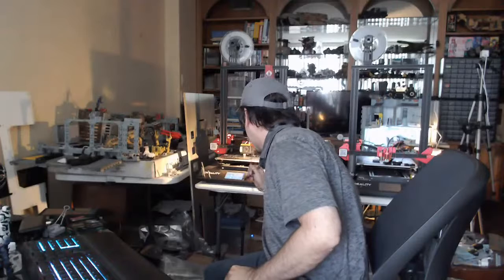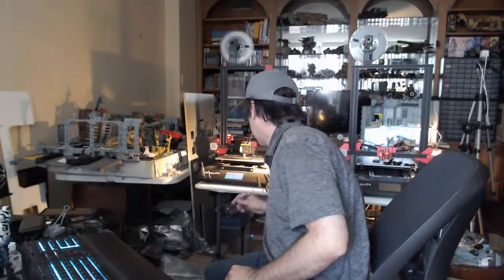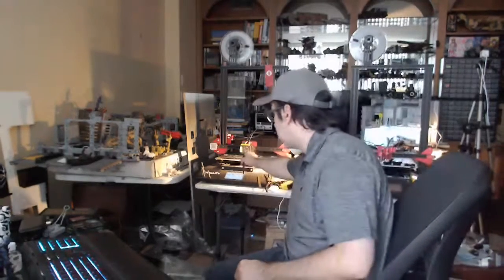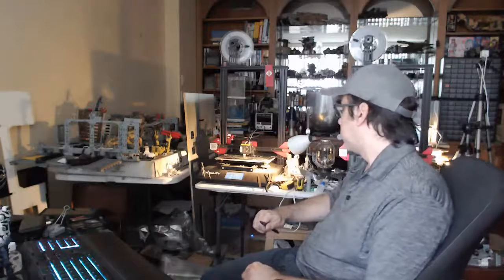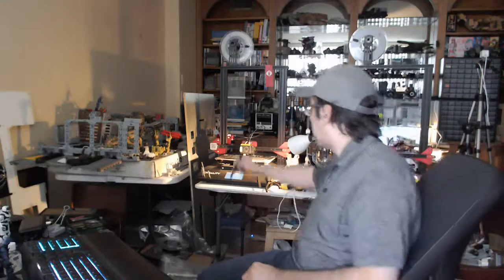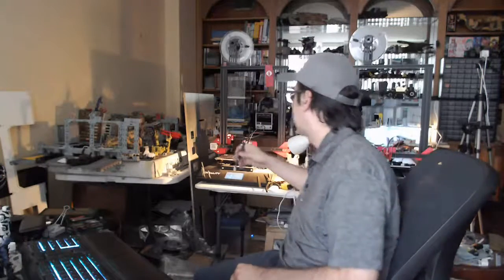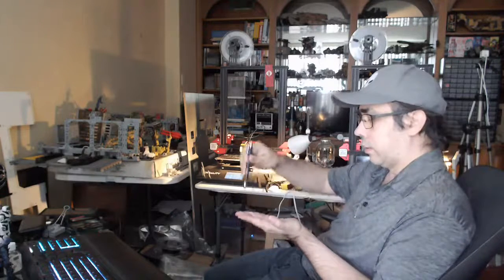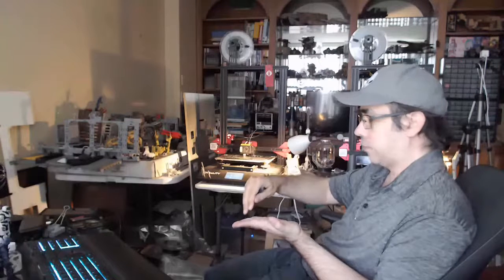Okay, so this is calibrated here. This printer has a function you can do completely manual, where it will plot points to find out if there are any uneven surface points, and it makes a little grid. Then there's a button that I just clicked where it will raise and lower the extruder in very, very small increments to parallel the rises and dips in the build plate.